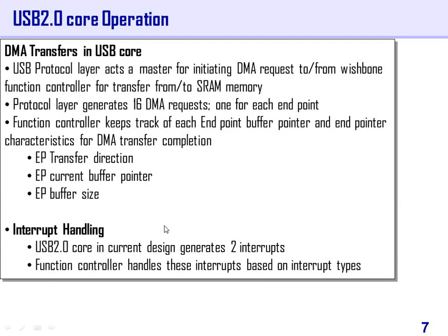Any doubts here? So the USB core generates basically two interrupts. Not to the host, not to my laptop. It generates them to the function controller. Inside the pen drive itself, as I said, there is this function controller.